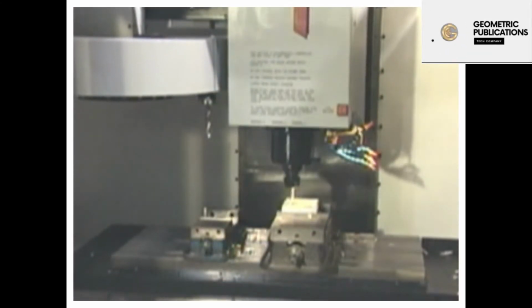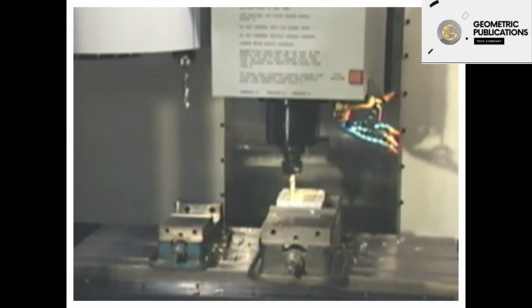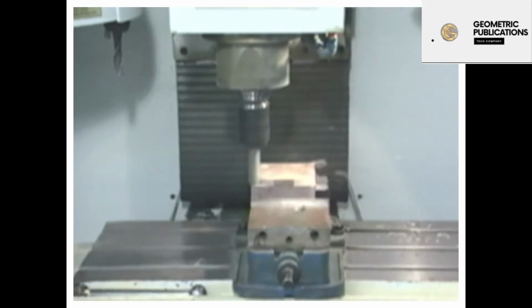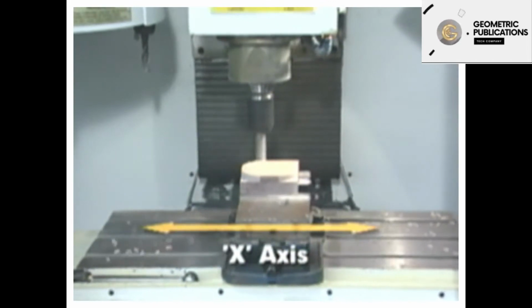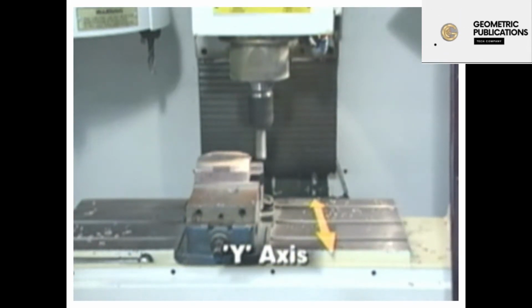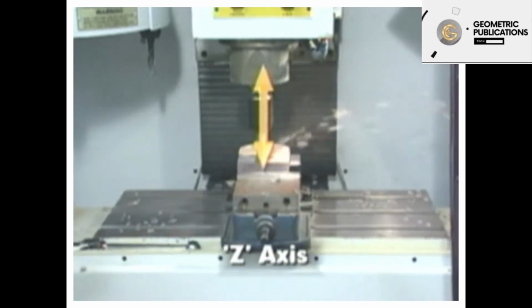Because of the diversity of machine tool types and applications, this program will concentrate primarily on the basic computer numerical control principles of a vertical milling machining center. The vertical milling machining center typically has 3 linear axes of motion, with each assigned an alphabetic designate or address. The table's motion side to side is called the x-axis. The table's motion in and out is called the y-axis. And the head movement up and down the column is called the z-axis.